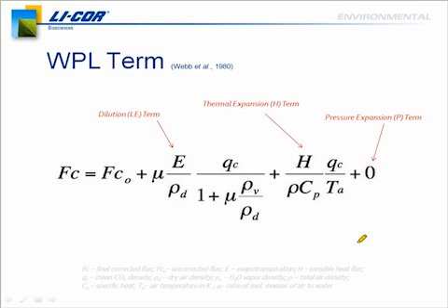With the 7200 here, and utilizing a standard 1 meter intake tube, the tube can attenuate about 95 to 99% of temperature fluctuations. That was found again by Clement in 1998. And it depends on things like the flow rate, the ambient H flux, surface roughness, thermal stability, and instrument height, for example. So the remaining 1 to 5% of the temperature fluctuations that still might occur can be measured with those fast temperature sensors inside the cell.